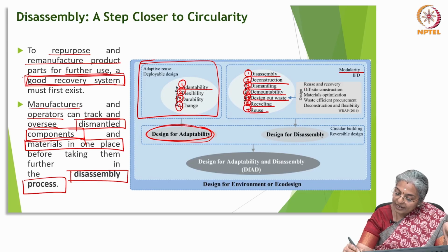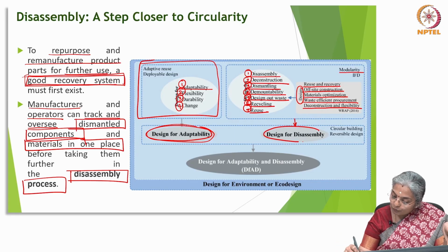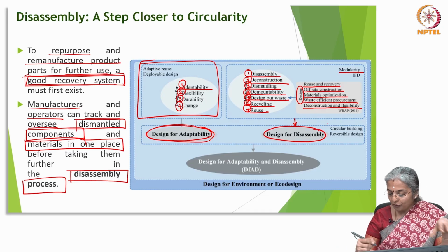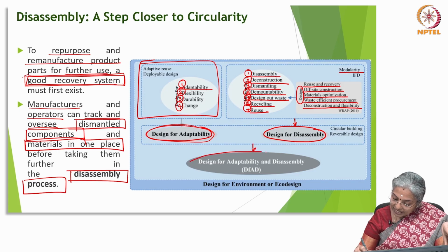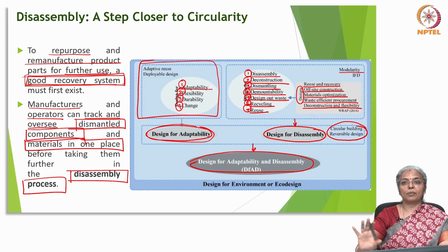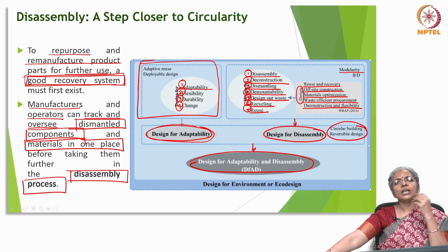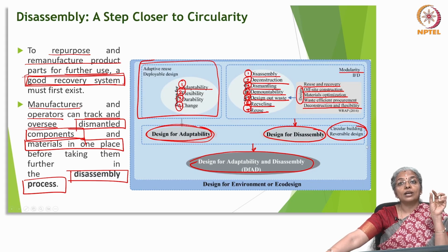And we should be able to design all of this for reuse and recovery, for off-site construction, for optimization of the materials, for waste efficient procurement and deconstruction and flexibility. Both of which will contribute to design for disassembly and adaptability, with circular design and reversible design as the primary motive. Now, what is design for deconstruction?